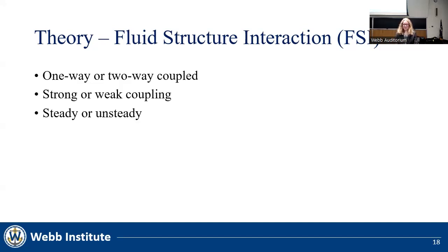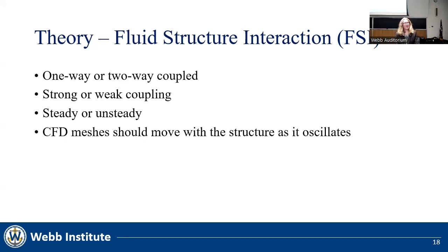Finally, scenarios can be steady or unsteady. In steady cases, the deformation does not change with time. And in unsteady cases, this deformation changes with time, and wake oscillations and vortex shedding can be observed. Additionally, the mesh in an FSI run needs to move with the structure as it deforms.